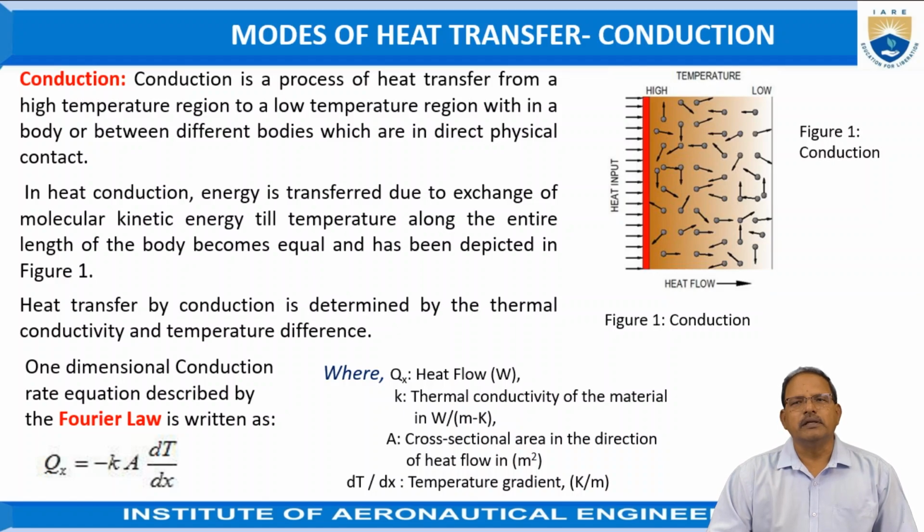The heat transfer by conduction is determined by the thermal conductivity and the temperature. According to Fourier's law of heat conduction, the amount of heat energy transferred is directly proportional to the temperature difference and thermal conductivity values. The equation can be written as Qx = -K dT/dx.